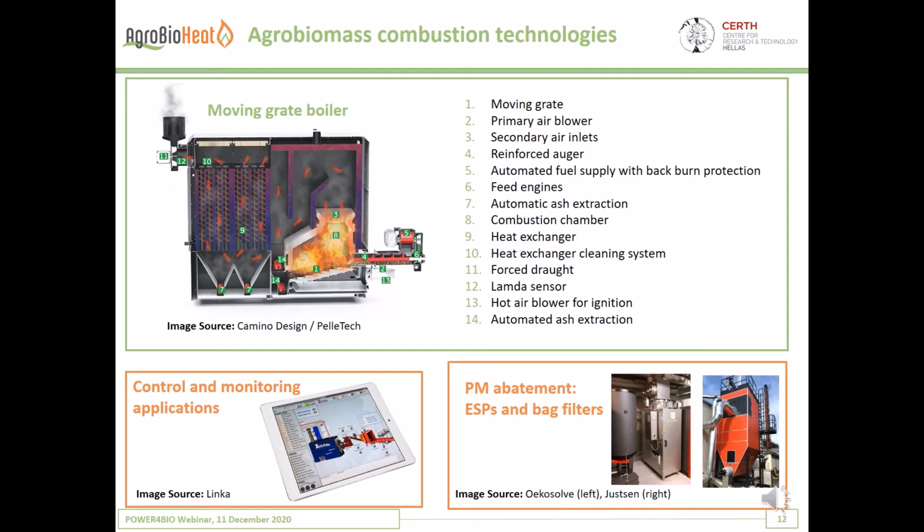On the other hand, there is also the issue of how you can control emissions from such a facility, and I would say the state of the art there is the use of either electrostatic precipitators, ESPs, or bag filters, which can control particle emissions. And when it comes to other types of pollutants, there are other things that you might be interested in employing, for example, lime injection for control of sulfur emissions, or systems like selective non-catalytic reduction for the control of NOx emissions.